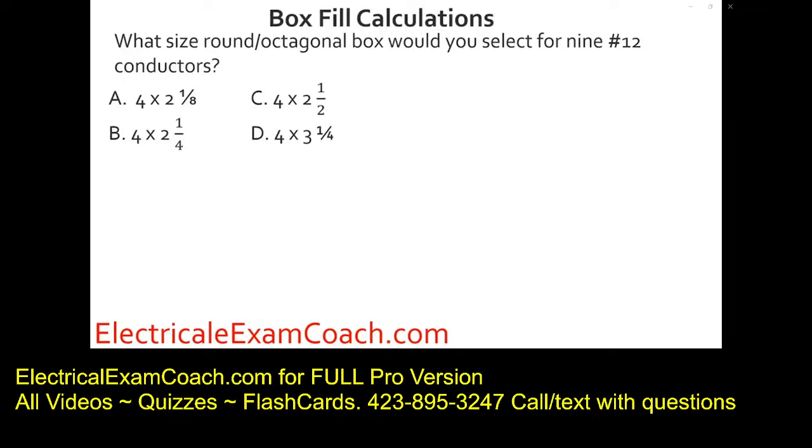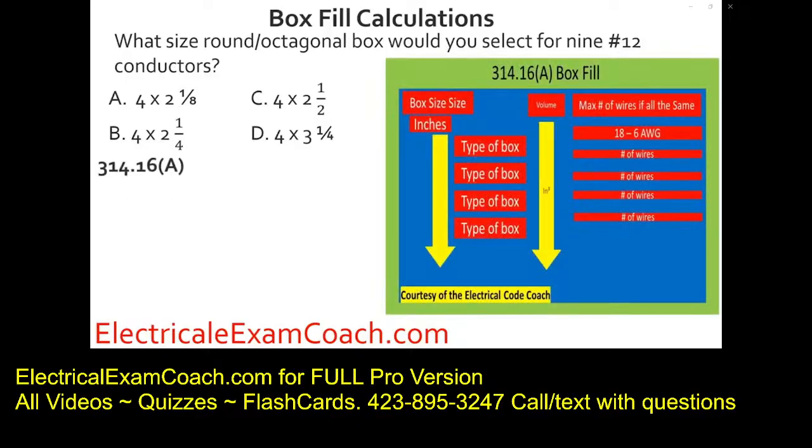Now, let's do some practice questions and get to it. What size round octagonal box would you select for 9 number 12 conductors? For this one, we're going to be using table 314.16(A). We're going to start here and find our gauge of wire. Then we're going to come down and find a box, making sure to cross over and double check that we don't stray over into a different style box. We want to stay in the round octagonal. We find our conductors, we find the one that fits, we slide over and double check ourselves, and we're going to select A. Great job!